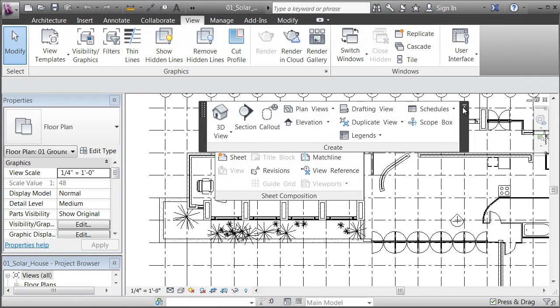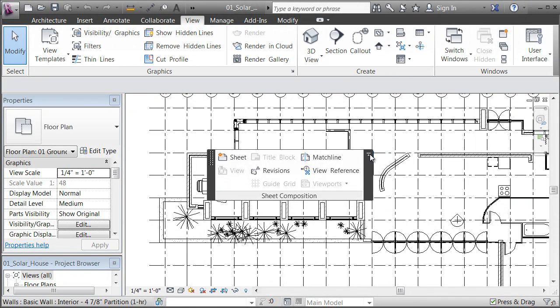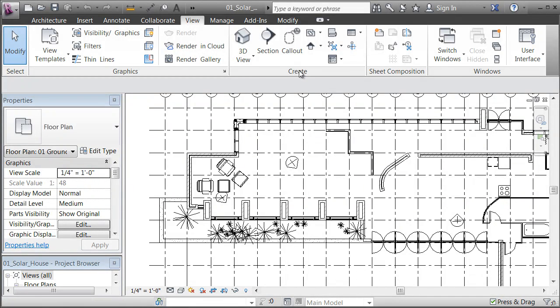I'm going to suggest for the purposes of our class, you don't want to do that, because it'd be difficult sitting down at a different workstation and seeing different layouts of the interface. So we'll try and keep them all looking the same. Although because of real estate, because this drawing view might be limited on your monitors, you can take the components. For example, this component is the project browser. This is how you navigate and move between views.